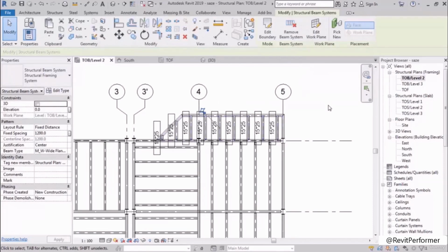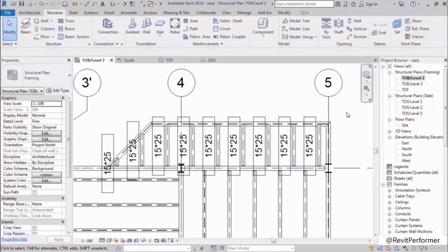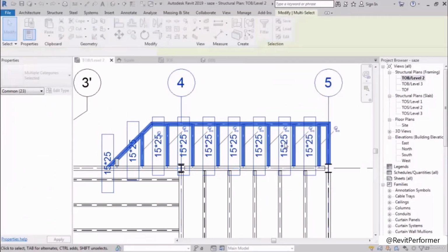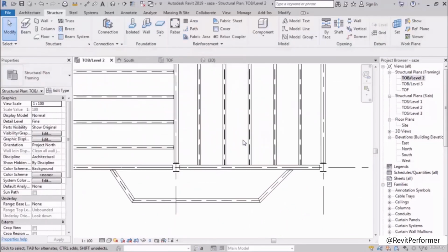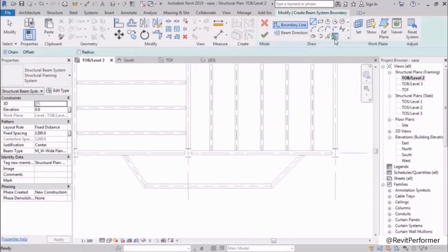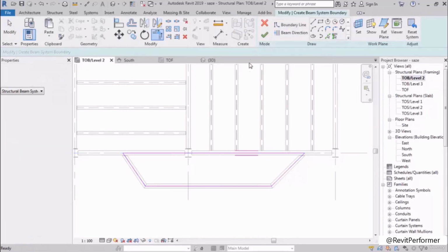When the beams are all done by this method, you can also see the names of the beams, but we don't want to see that, so we open a box, filter, select, and delete. Right? Here's the same thing. Let's review. Beam system, automatic does not work. Sketch, pick support, click this and this, and then make it organized, and then finish.